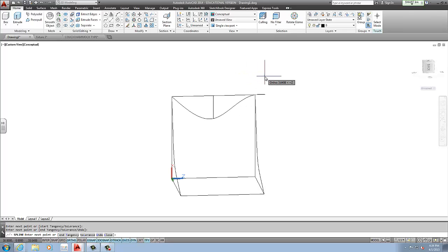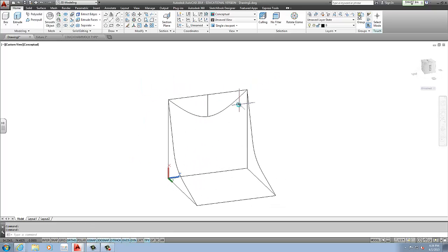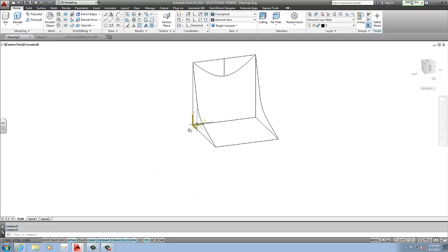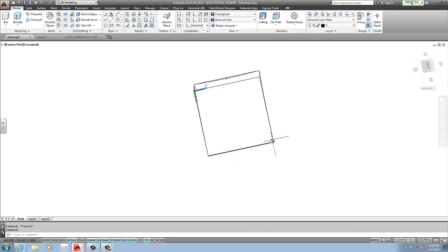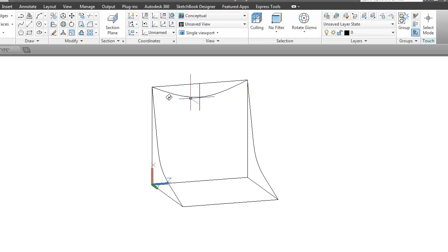So when I do the spline, I have an end point, a midpoint, and a third reference point. And here I don't need to worry too much about the X and Y coordinates because it has all 3 points. It doesn't snap onto something, and you're not clicking on space, so you don't have to worry about that too much. Once I'm happy with that shape, which of course I can adjust, I can work with the bottom shape. Now the option for the bottom is I can use this same shape as up here or design my own.